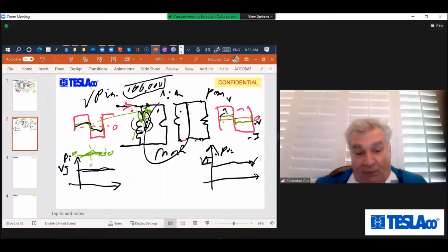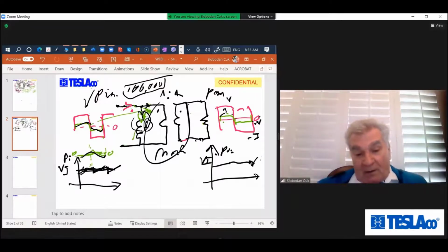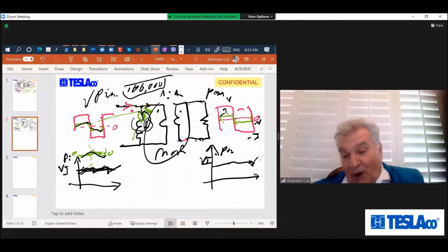But if you take into account this triangular current, you multiply this red with the square wave here, and you're going to get this sawtooth-like waveform, which has the same average VI and has a ripple at the top of it. Now, do you say that's storage? No. An AC inductor doesn't store energy.